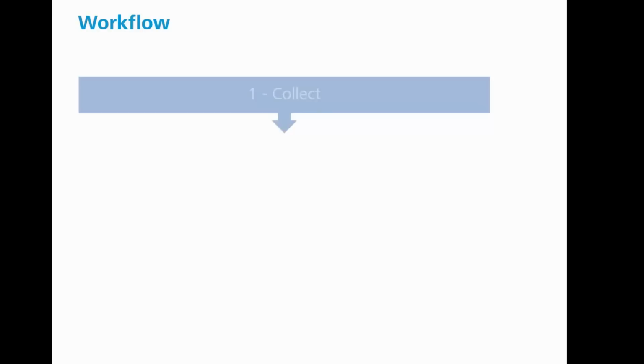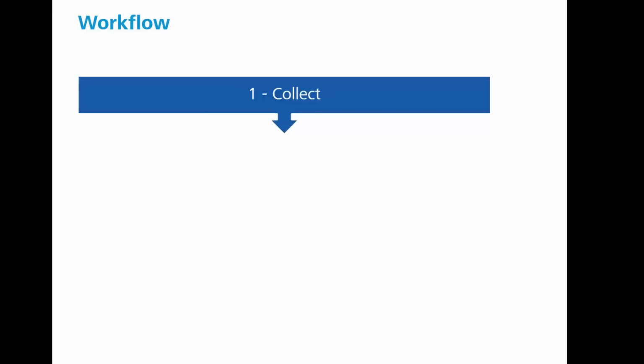That may be Revit files, IFCs, DWG files, MicroStation models, whatever it may be. You can bring them into Navisworks, combine them into one whole project model, and then deal with it from there on. And any and all of that, if you can open it in Navisworks, you can use it for rendering in the cloud.